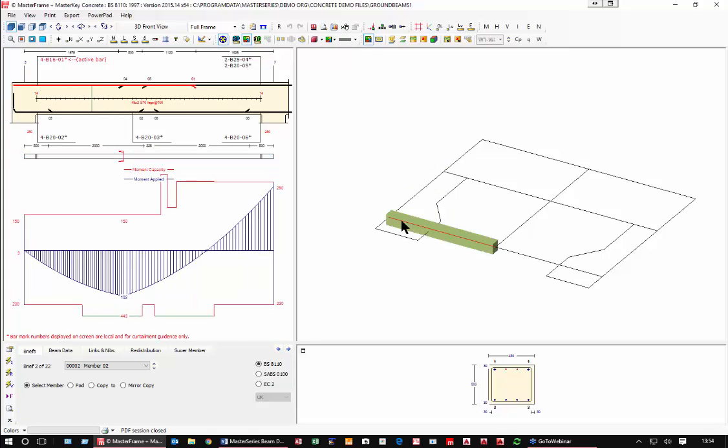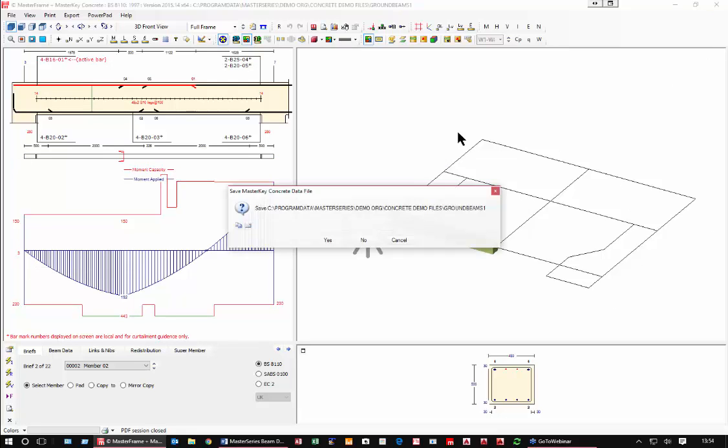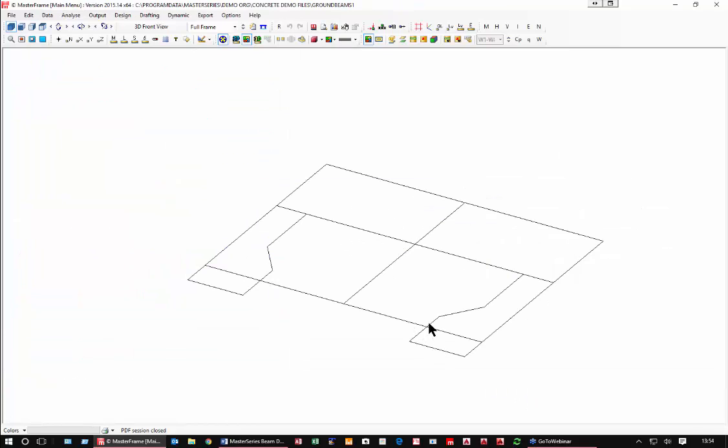Now, a little trick for you, obviously, because you're going to want to know how I've done this, is how to set all these little pins. Well, provided you don't have a horrible cantilever that's not got what I call a backspan, so these cantilevers all have backspans, then it's a very simple process. You do not have to come in and do what I've done here and put all these pins in.